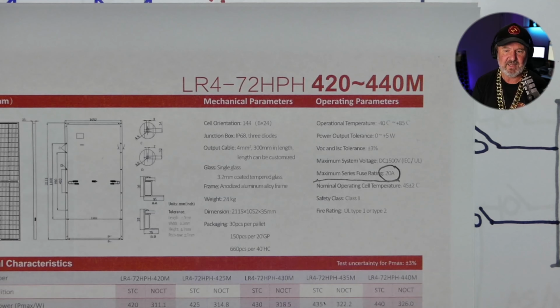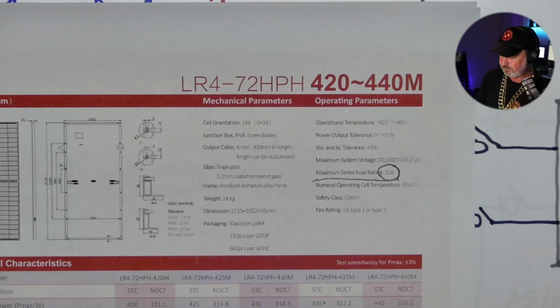It sounds very archaic, this muslin and tissue paper, but the purpose is to see if there's any scorching. So after 2 hours, they stop the test and inspect the tissue paper and the muslin. There should be no scorching on either. So you haven't thermally overloaded the module. So that means this panel can, under fault conditions, accept up to 20 amps. And they call it a series fuse rating because the most common way of limiting that current is to use a fuse in the string. And the maximum size they recommend here is 20 amps.